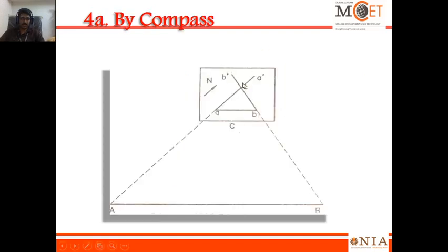With the instrument at A, sight A, draw a line and extend it towards A dash. Similarly, draw the ray by bisecting the station B and extend it. If it meets at a point, it is the required point, since we have oriented towards the north already. So this north can be plotted here at the top right corner predominantly. If there is any congestion, we can have it here also, no issue, right? So the point C can be found, but it is a very rough method.